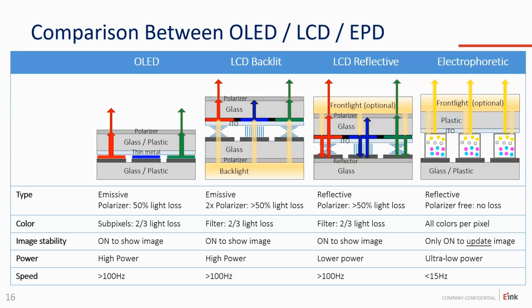So an LCD starts with a backlight, then an entry polarizer, where you lose, of course, 50% of your light. Then, depending on how you switch your LC, the polarization state is changed or not. And that causes the light to either go through or be blocked at the second polarizer. Pretty straightforward. And then a color filter in between again to create color.